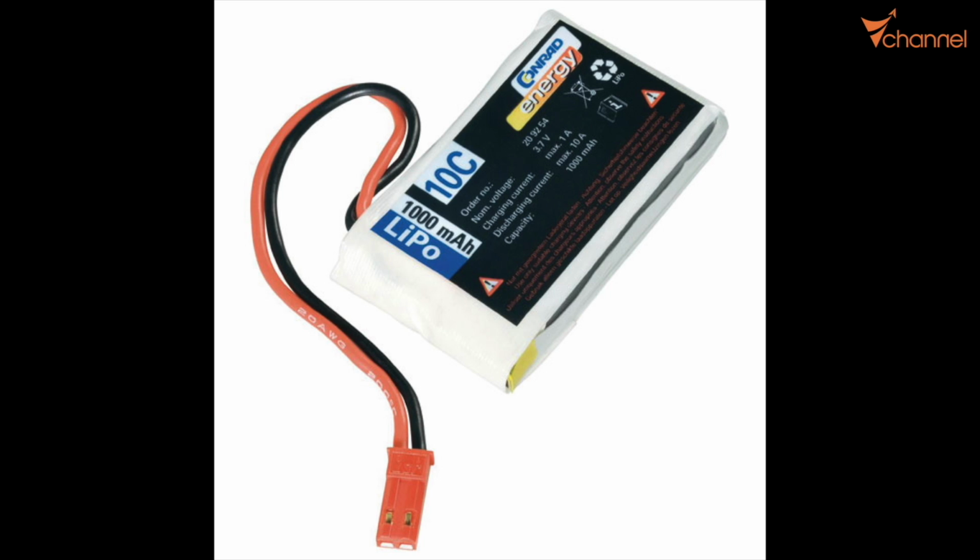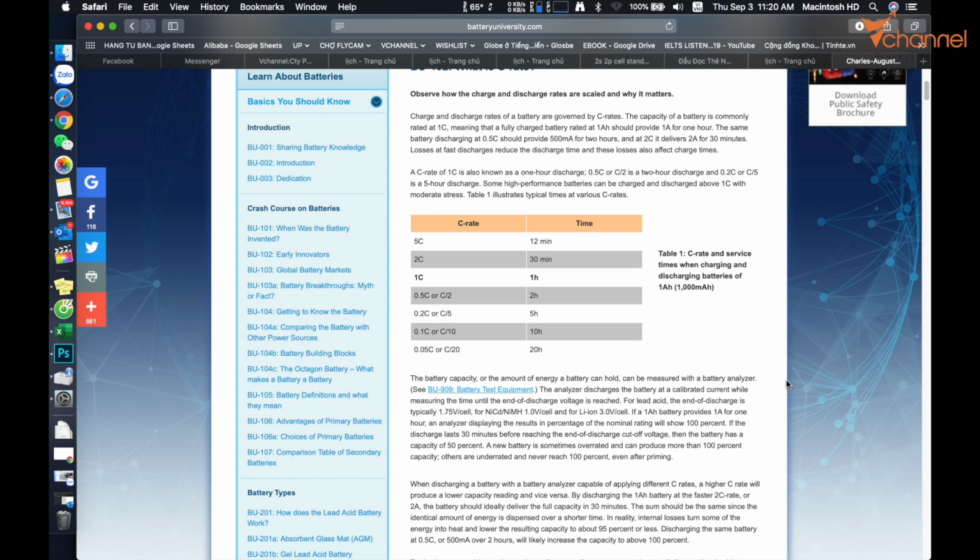That means this battery allows a discharge current of 10,000 milliamperes. Actually, we can discharge more than that, but it will get very hot, have bad effects and damage the battery seriously. The longevity is decreased and it can even burn. So this is the maximum discharge for the battery.